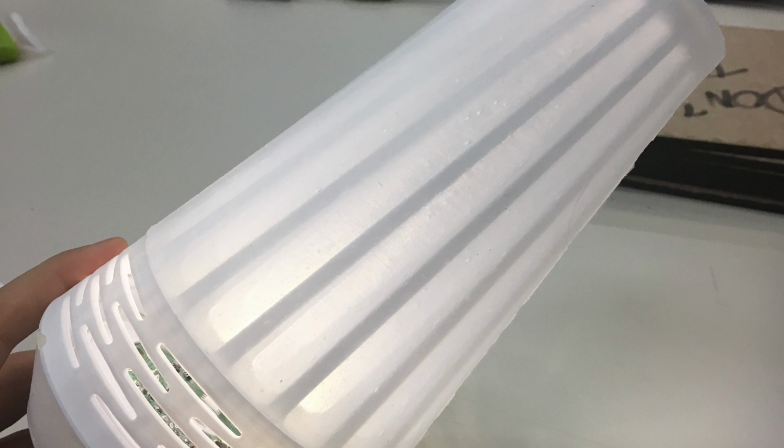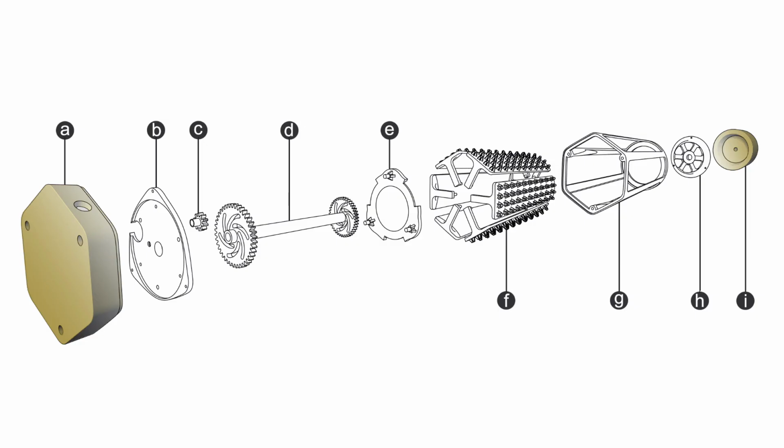We attended to a dynamic physical form with materials at hand by experimenting with and selecting materials. We 3D modeled a mold to test the deformability of cast silicone pieces. While the silicone-made lab shade can support long-lasting interactions, the cast lab shade pieces require a large force to deform its surface. This problem stimulated us to adopt elastic fabric to manifest deformation that is softer than silicone. While the elastic fabric can sustain repetitive deformation over long periods, there was a need to craft an actuation mechanism to deform the selected fabric.